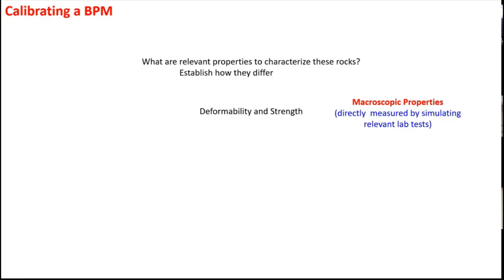And where are the forces and stresses when you squeeze it? And then we have concepts of strength. Strength is a slippery beast. It all depends on what sort of strength, right? When you say strength, do you mean complete failure? Do you mean the beginning of damage? Do you mean operational failure? Maybe it's failed a little, but it's still safe enough.